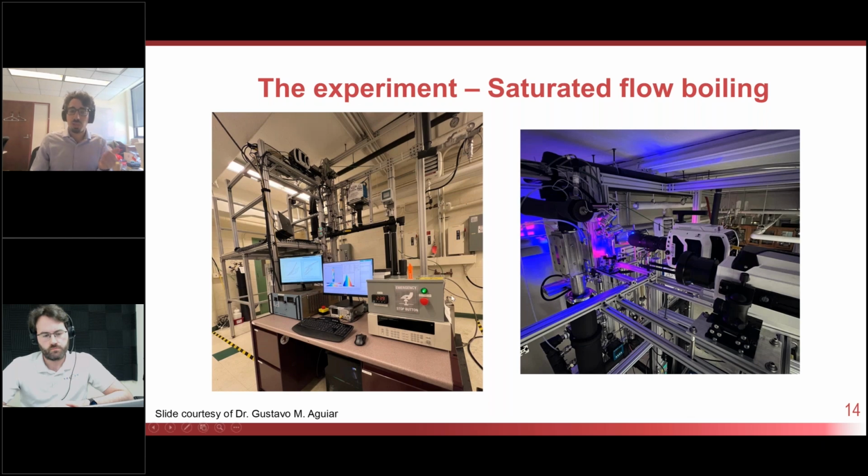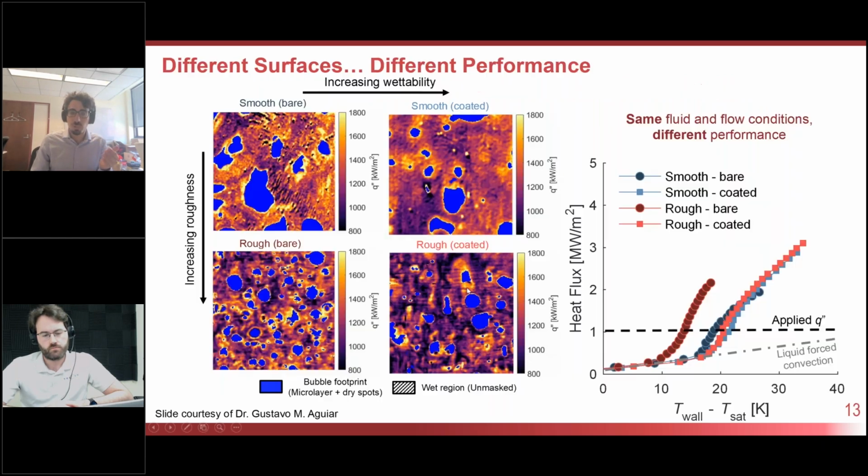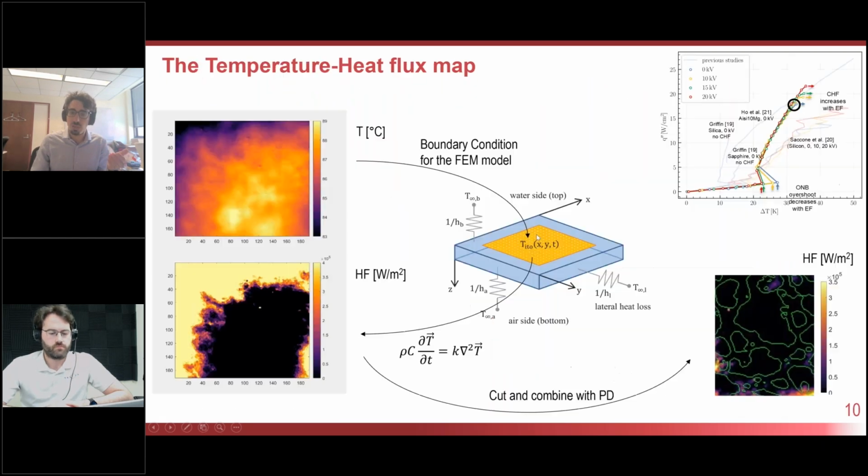By doing that, we can do the inverse conduction problem and find the heat flux, because we know that we have a 1 millimeter sapphire below and this temperature map on top. If you're measuring on a thin film of metal, then you're going to need to use the temperature at the bottom as boundary condition of your problem. I'm not sure if that works. I have never tried.